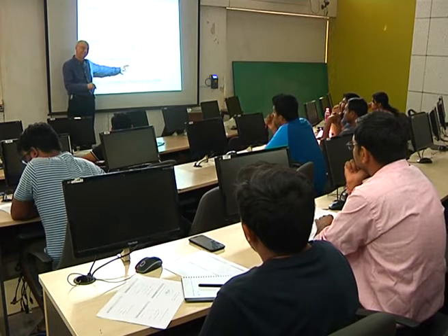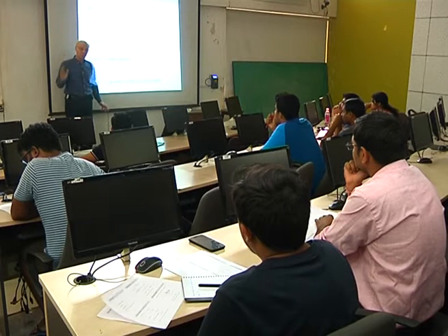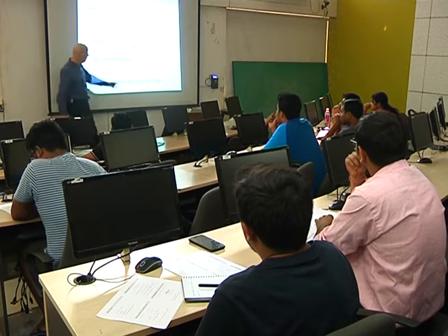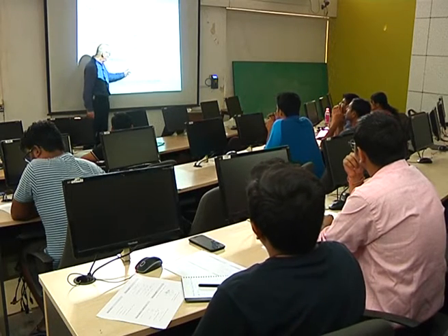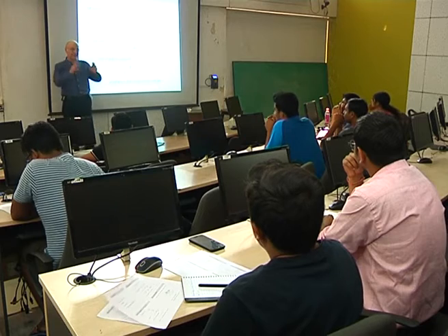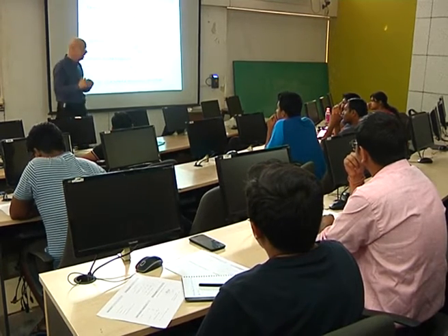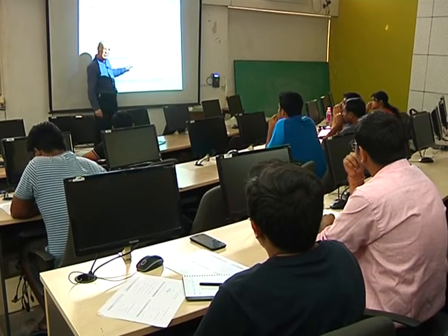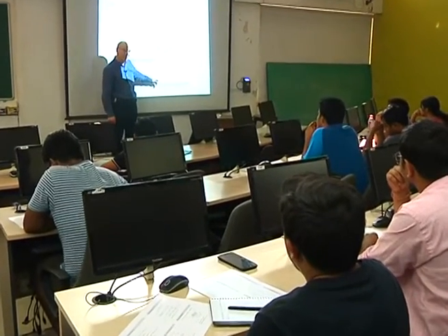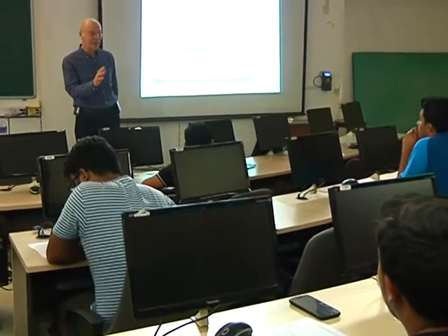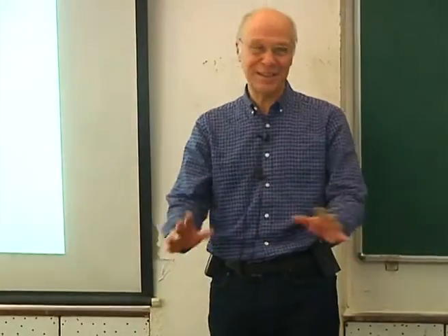And that's the answer. So you could test that. If omega was constant in y, then it'll be the same at 1 and a quarter, and then 1 minus a quarter is 3 quarters. So that's right. Now the question is, does it work when the vorticity, when omega varies with y? So it'll be a quarter at a quarter and 1 at 1, and you get a quarter, so it's 0. Okay, so it's right in the two cases, constant and linear, which is all we're fitting to 2 points. It is the right thing to do.